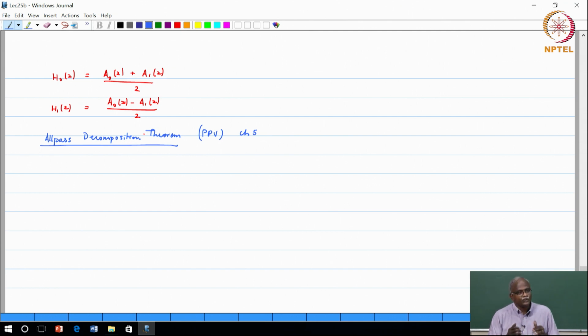We will try to see whether we can look at the linear phase part and the all pass part, and combine these in some way to get a perfect reconstruction filter bank, because I want to eliminate phase distortion and magnitude distortion. So, one more step and we will work towards perfect reconstruction.